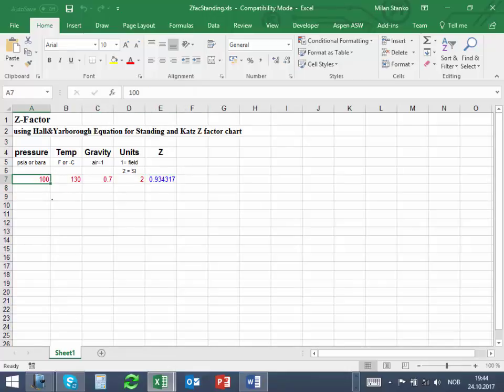So you can, for example, just verify. We have here SI, so it's in bar. We are saying all the time that at 1 bar and ambient temperature, let's say 15.56, the C should be very, very close to 1, 0.9997. If we go to reservoir conditions, let's say a reservoir that has 300 bar, and what temperature do we put? 100, for example, then you have some deviation, like 4%. If we go for very high pressure, some reservoirs in the North Sea can have up to 1000 bar, 800 bar, then you see the deviations start becoming bigger and bigger.